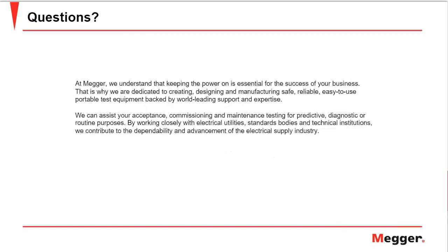Yeah, that's a good question. As Sugosh mentioned, the second harmonic is used to protect against magnetizing inrush conditions. We don't want the transformer differential to operate for those conditions, so the second harmonic will restrain the differential from operating. But the fourth harmonic is a multiple of the second harmonic, so it provides some added margin for non-operation during the magnetizing inrush.